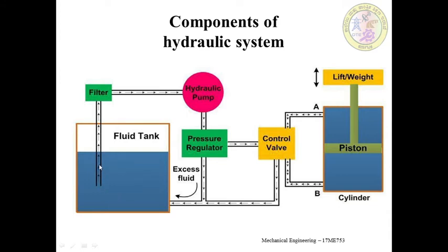Pressurize the suction line, here the suction line is there, which means the oil is taken through this line. The filter is the element through which this suction oil passes, so that any foreign particle is trapped in the filter. So very clean oil travels through this line and reaches the pump, which means the suction action of this pump takes place from the storage tank to the pump.